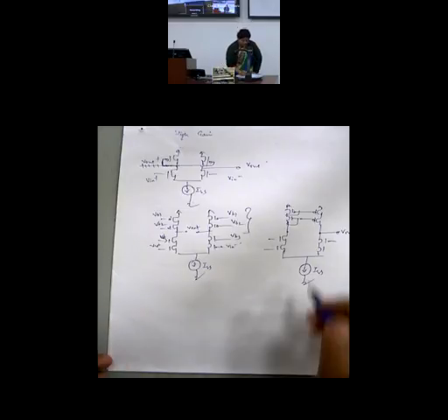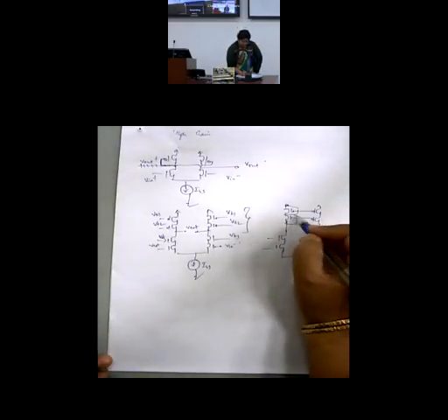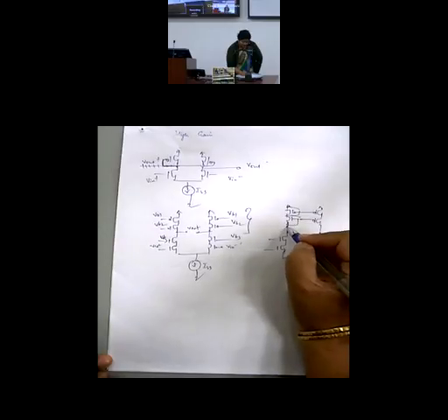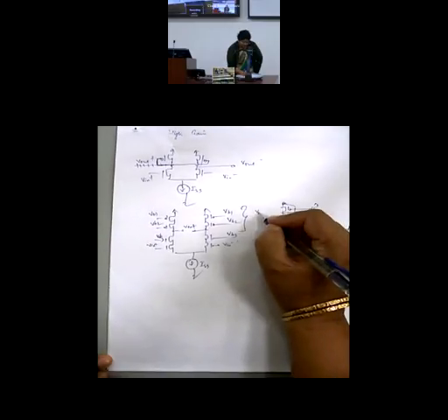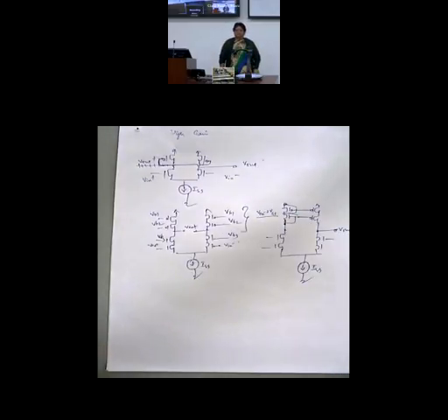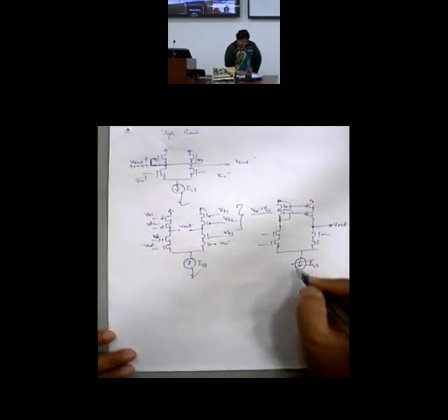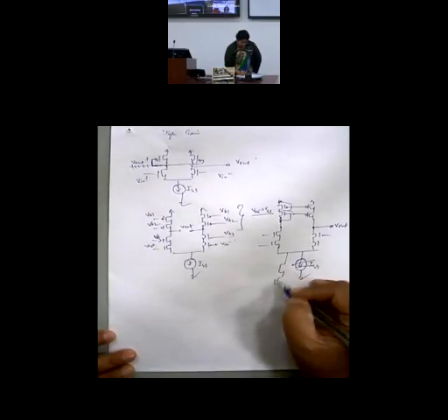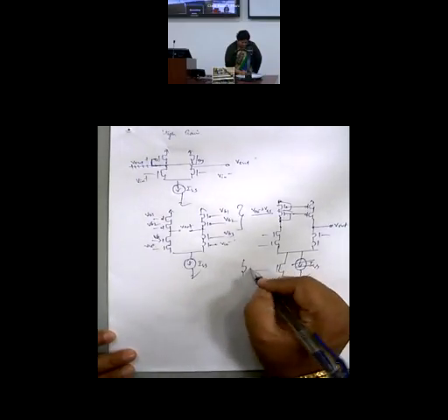Now this takes 1 VGS and 1 VGS, 2 VGS. So this point needs at least VDD minus 2 VGS headroom. And if VGS is 1 volt, you are losing 2 volts. One problem is this. Same thing is here. If I replace this with a cascode current mirror, I would be losing on the headroom.